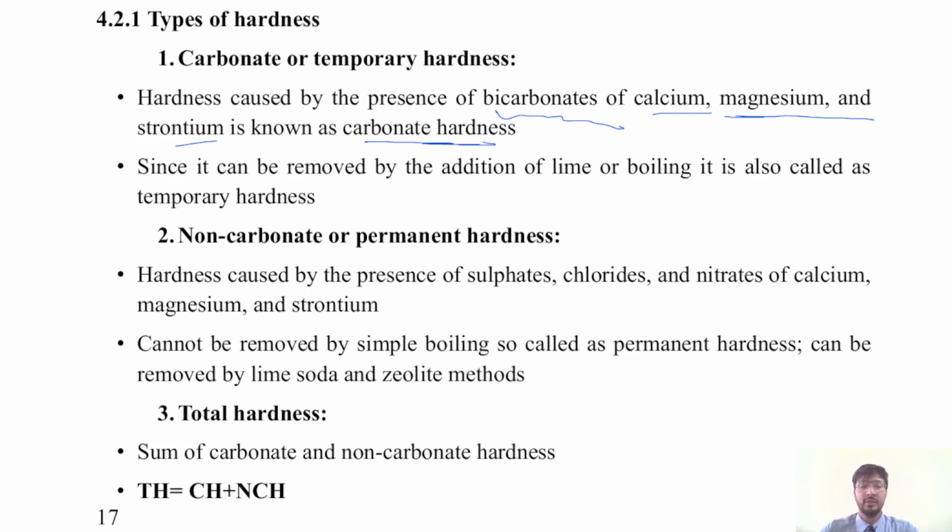Another is non-carbonate or permanent hardness. It is caused by the presence of sulfates, chlorides and nitrates of calcium, magnesium and strontium.